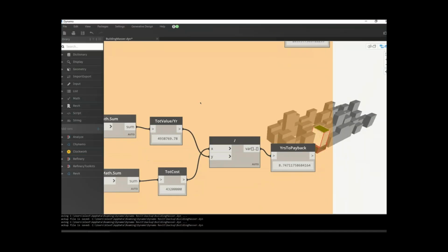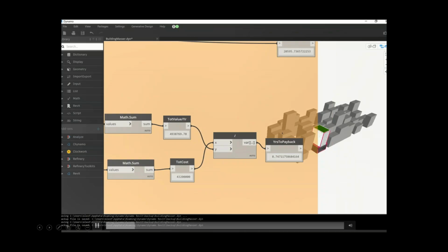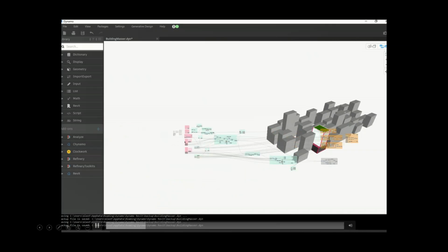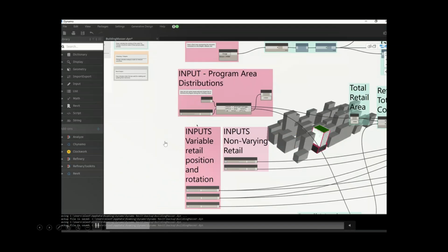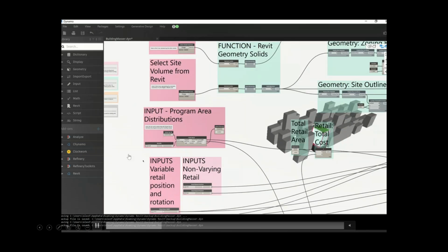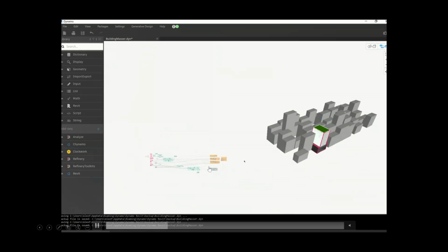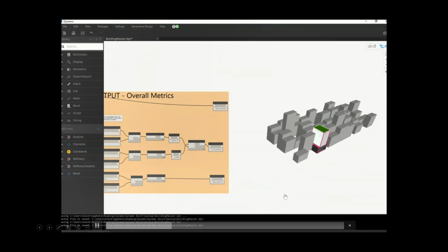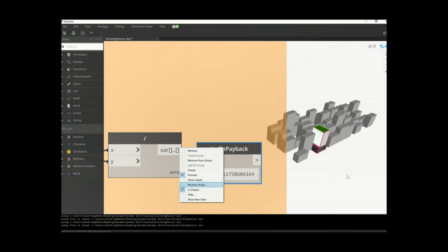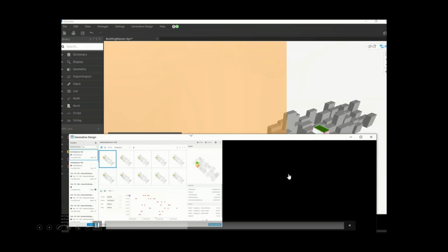So how do you get this solution into Dynamo? Well, you right-click on this and set this as an input here, as you can see. So this would be an input of our study, and for the output there are a bunch of parameters here that you can right-click, for instance years to pay back. Then this is set as an output, and then you run your generative design.